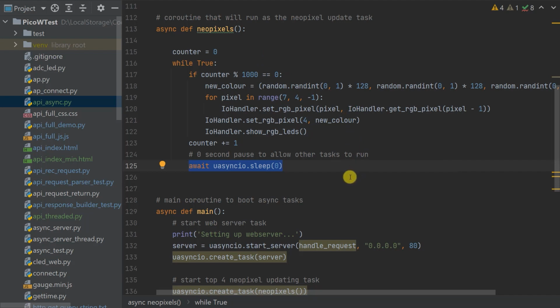So that is a simple one, and we could, if we wanted to, then, we don't have to do it all in one task. We could have perhaps one task running to monitor our inputs, and that would build up an input table. We might set off a second task which maybe would handle motors and various heating elements depending on what we're doing and so on. And we can really just have them all in their own little separate control loops, and each of them then running in parallel.